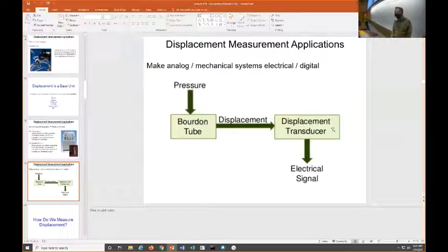If we instead put something on there that measured the displacement, like say we put a strain gauge on there, and we put that strain gauge into a Wheatstone bridge, we can get a voltage out that we can calibrate, so our DAC will get us dynamic data that we can monitor remotely, or we can do some post-analysis to it. So all those benefits of a modern DAC system.